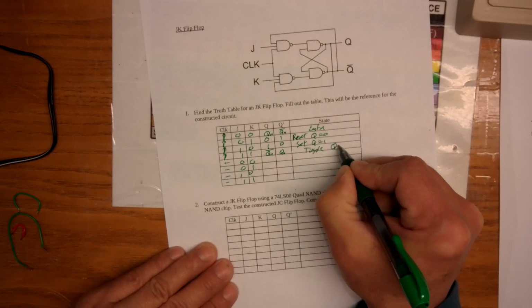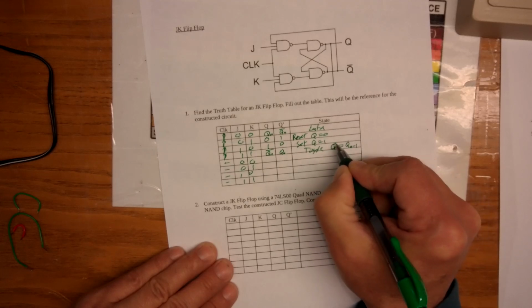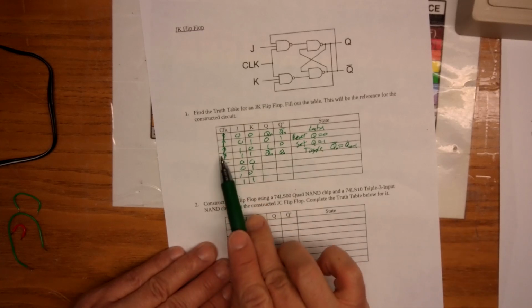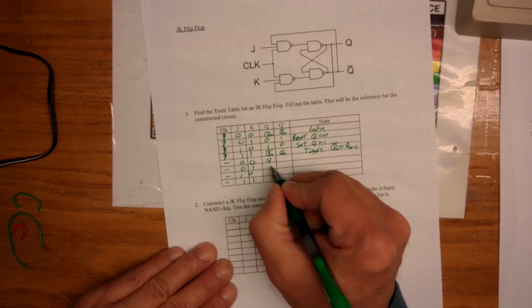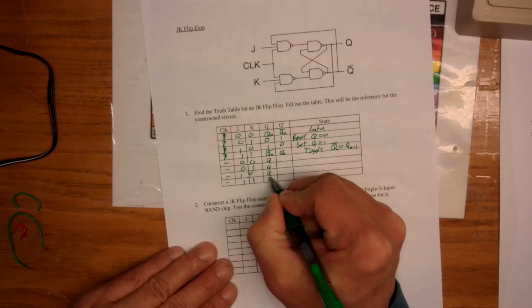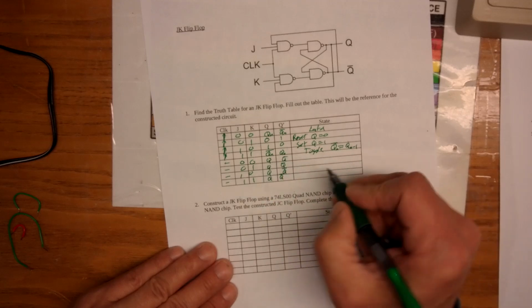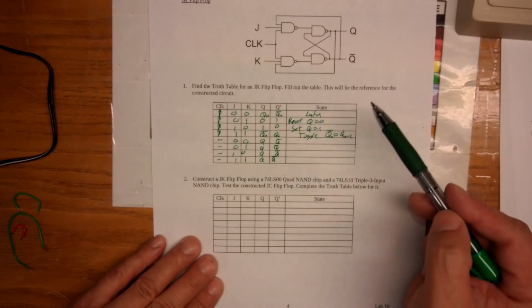Right, so Q in is equal to the last one inverted. If you're not doing this, what these should all show is that it stays exactly the same. So you could put, hey, this just stays at Q. This stays at Q naught. And you can just go down and put no change. So you'll see this a lot of times in what's called an excitation table.